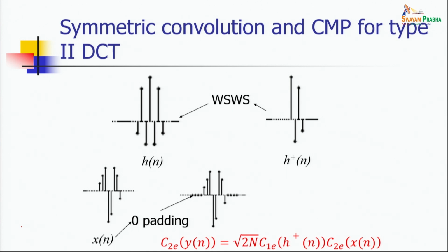And another trick we have to use in this case is zero padding. Zero padding is used for bringing the filter to the required length, sometimes the required length of n plus 1, as I mentioned. So effectively, I will be doing zero padding at this end.